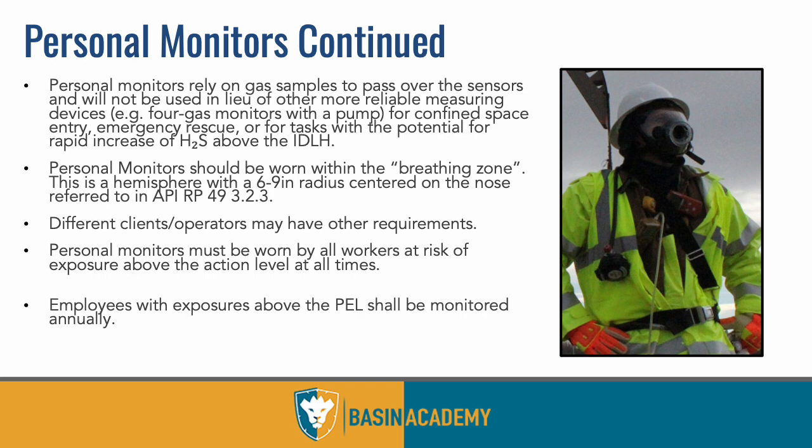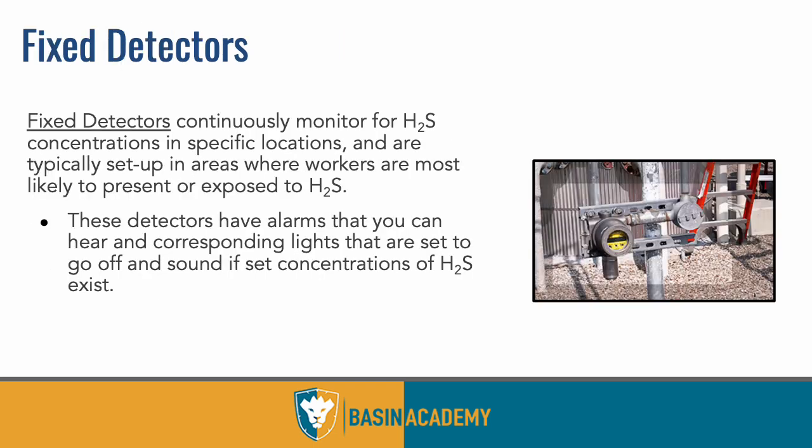Personal monitors must be worn essentially by everyone out here that is at risk of H₂S exposure, which again, is on every well site. It's in every ounce of crude oil. In every CFM of gas, the question is not is H₂S present. The question is how much H₂S is present. And that's really the main function here. So anyone who's exposed over the PEL should be monitored on an annual basis, making sure that they're not getting sick over time.